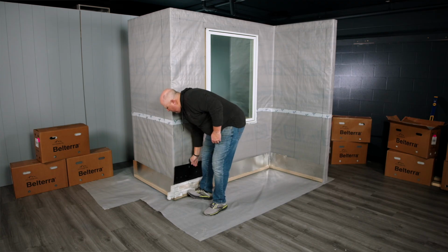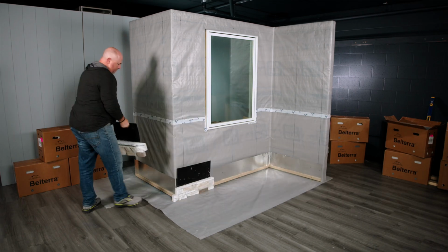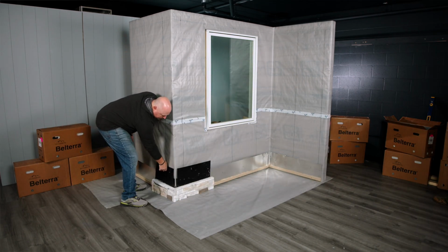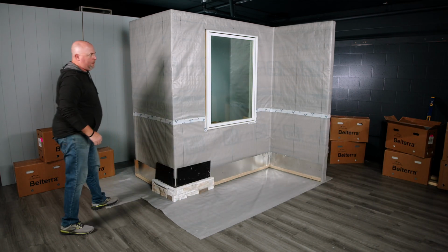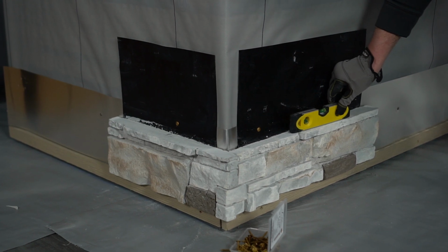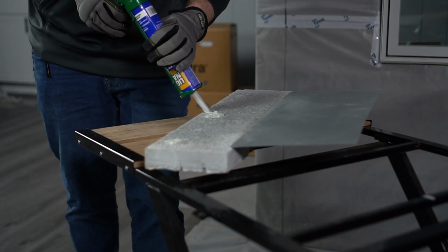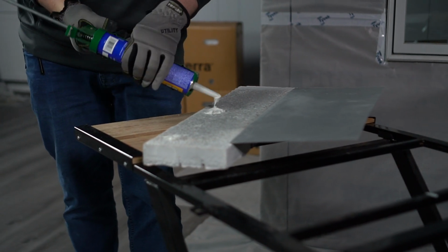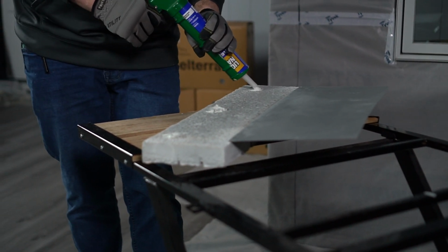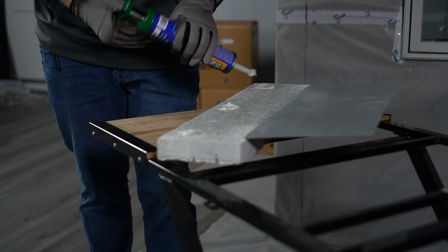Select an outside corner, a vertical transition, or an inside corner in that order to begin your course and work across the face of the wall, keeping level as you go. Apply a few silver dollar-sized dollops of construction adhesive to the bottom of the back of the panels on the initial course. Adhesive should not be applied in a horizontal line across the back of the panels.